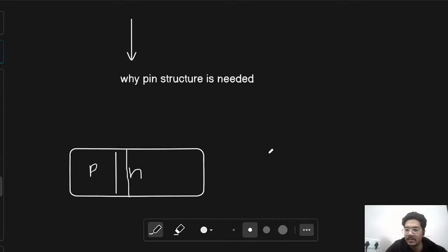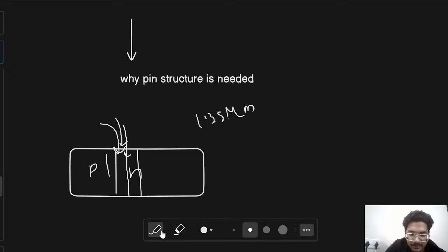At long wavelengths, like 1.3 micrometer, the photons penetrate into the semiconductor material, so widening the depletion region is needed to absorb more photons. We have to widen the depletion region like this. As we increase the depletion region, the device becomes more sensitive and the speed is reduced, but it is limited by the doping level.